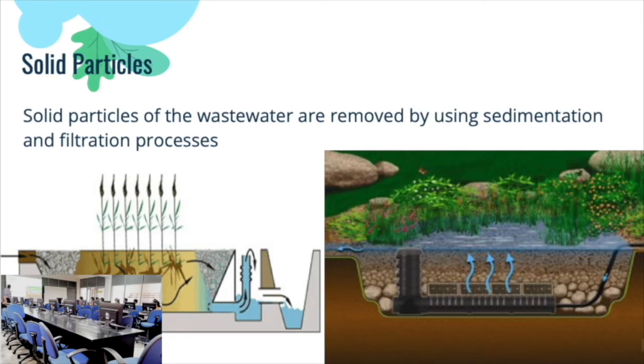So inlet water gets filtered in the inlet zone, and it goes through the root zone. Then if any sediments are carried from the middle range, they get deposited at the final stage in the outlet zone, and water can move away from the wetland.